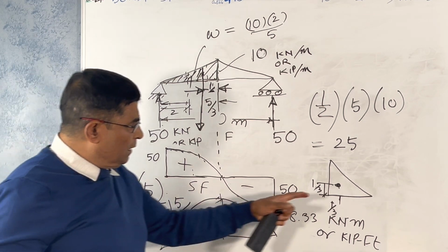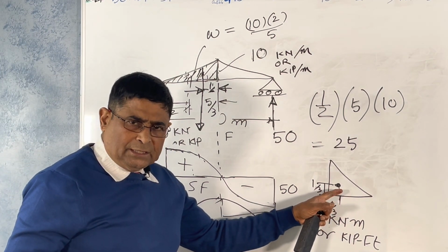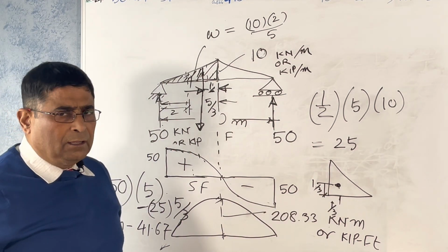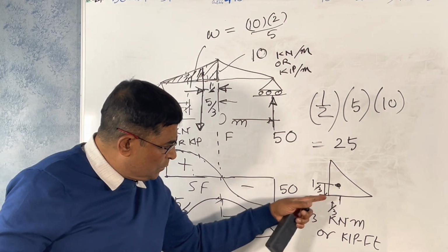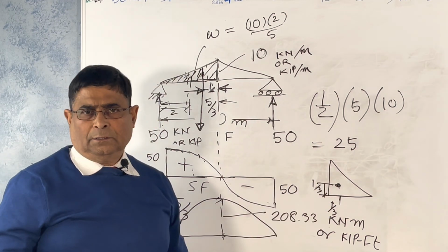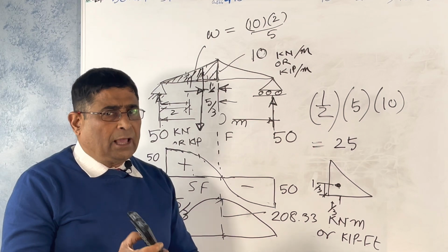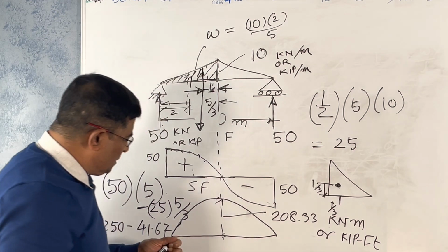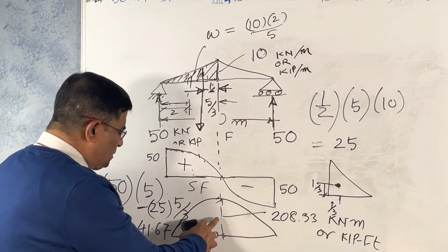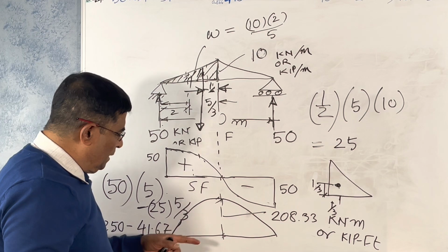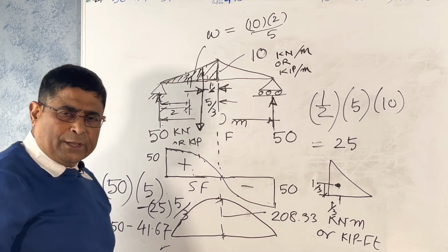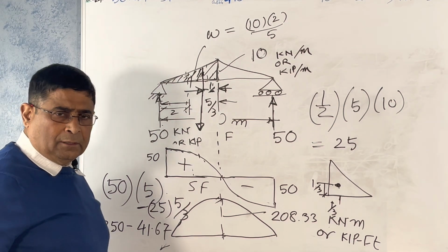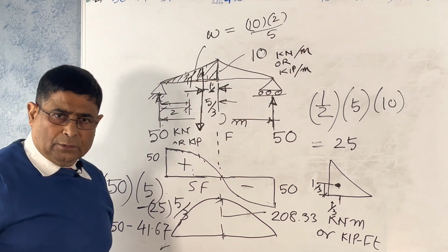In a triangle, the center of gravity lies at the 1/3 point of the length, either this way or that way. So this is the point, for the triangular loading. I'm telling you that in a nutshell. If you have an exam and you calculate this value, I write down the value there, and it will be okay. Or you can find out 1 or 2 points and calculate the moment. But it is easy because it is a symmetric load.